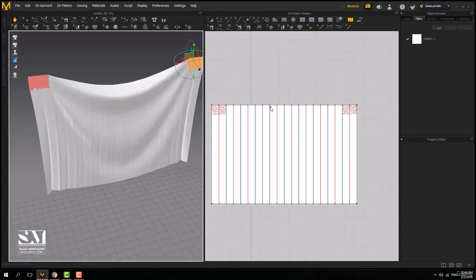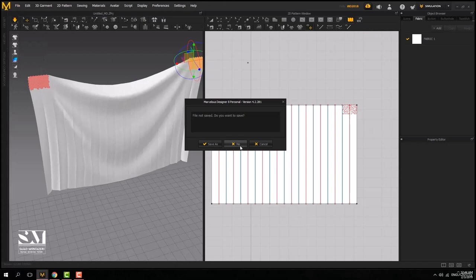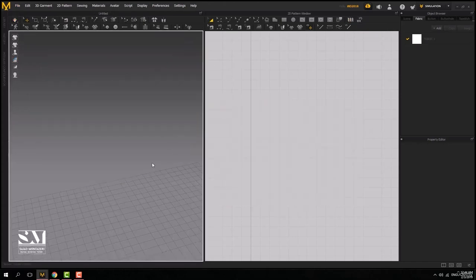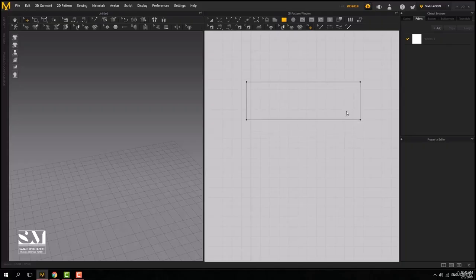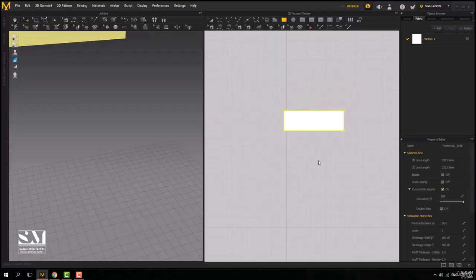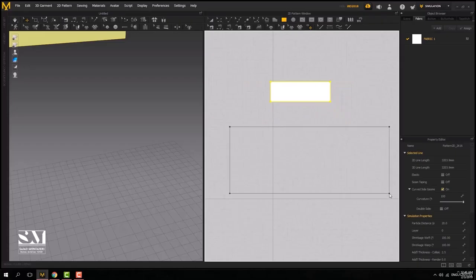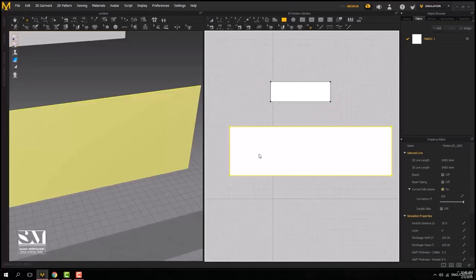So here, the next option we can use for plate modeling is actually a new option, which is plates sewing. Before that, I'll open a new file here. So click here, and I don't need to save this one. And in this new file, I'll draw a rectangle here. And also after this rectangle, I can draw a larger one below this one. Actually, because I want the wrinkles to show exactly as they are, using what we learned in this session.